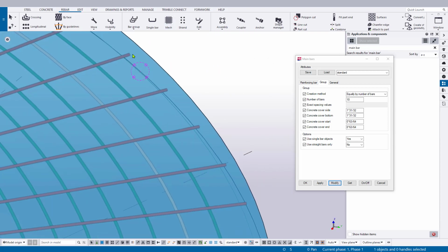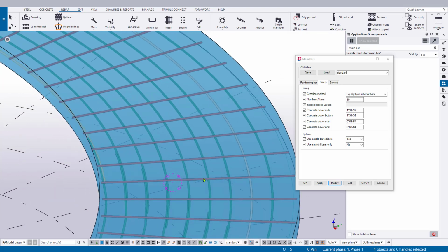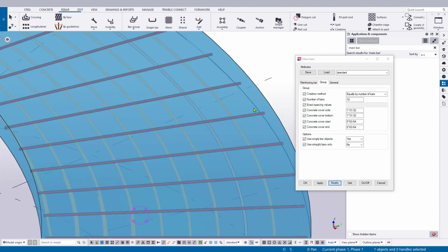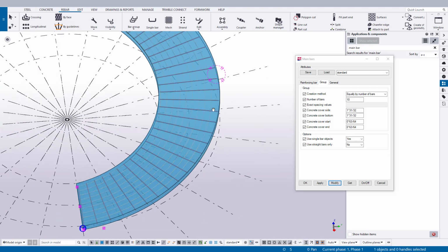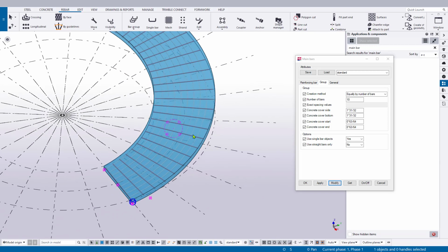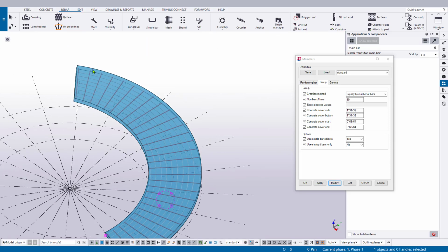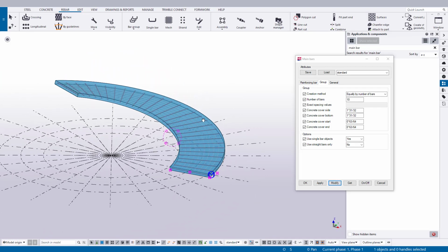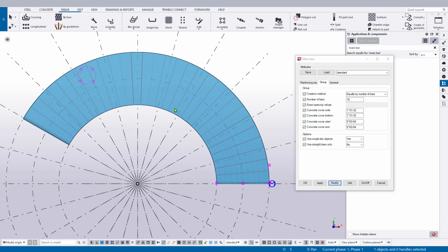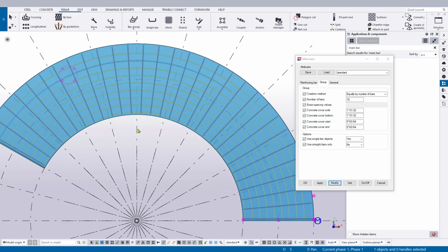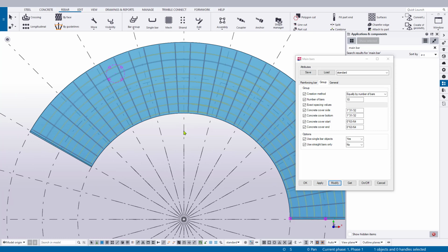But you may notice at some point on the outside where you have a bar that shows up as a single line and not necessarily a solid bar, right? And this is the result of the bending radius being compounded by the tool because of its offset. And I'll show you how to fix that really quick. But by and large, what you should do is apply the tool and inspect your result. Come in and play around with the options to tweak the specifics and get as close to your configuration as you can if it doesn't give you it 100%.